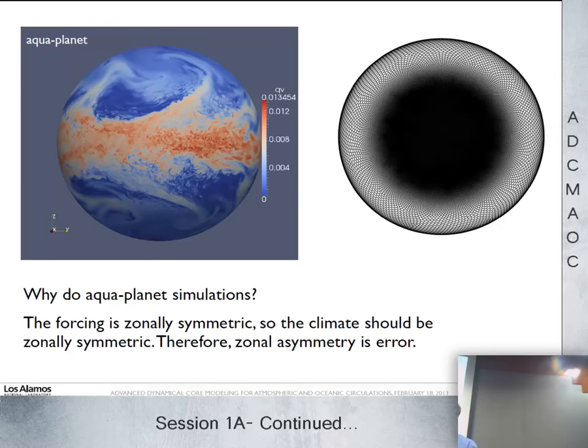The numerical method is exactly the same for every cell. And that is actually the reason we chose the conforming mesh approach, because in the conforming mesh approach, topologically, every cell is identical. And so you have at least the opportunity to have a numerical method that can then work on a variable resolution mesh.